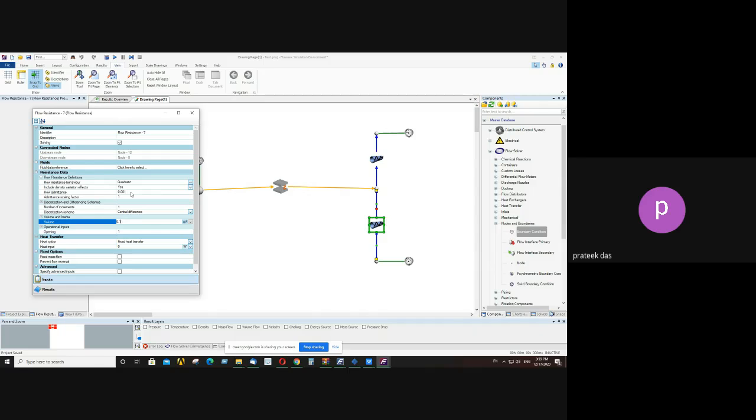So this f represents the frictional losses and rho V is the momentum change. If you make the density constant, like in the case of water or any liquid, then that will be proportional to the mass flow square.